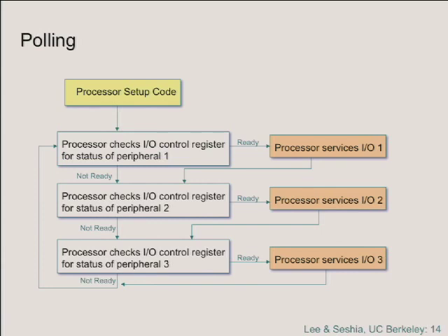So the way that it works is you do some setup initially, and the setup is basically just telling the external hardware that the way that it should notify me is by raising an interrupt request. Interrupt request is done on one of these open collector lines. Okay, the external hardware pulls the line low, and that's a request for interrupt. And so you tell the external hardware by just writing to a memory mapped register saying, I want you to interrupt me when something happens.